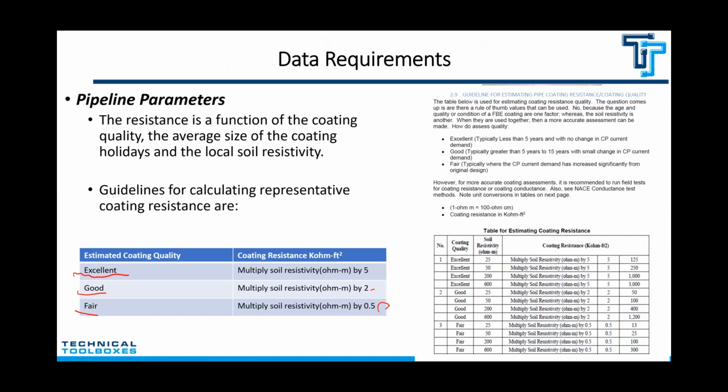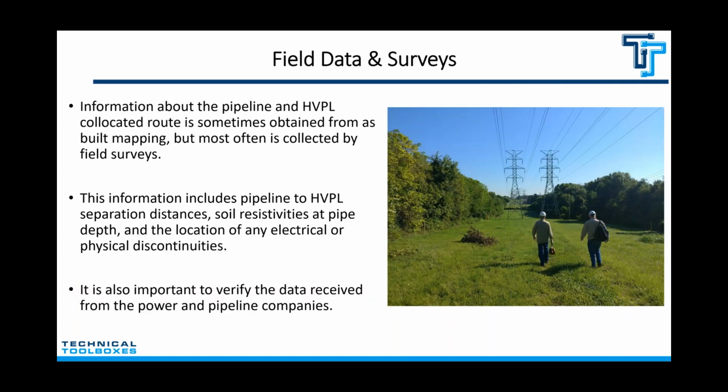Again, that has a big impact on your model, and you'll have several of those throughout a model. If I've got 4 miles of pipeline, I might have different soil resistivity 5 or 6 times along that pipeline. And each of those will be excitation points that will affect that. So you have to watch that real close. Okay.